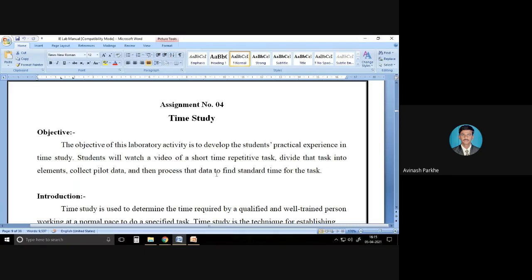How much time is required? 2 minutes. This is a rough value. Sometimes I can move from machine 1 to 2 within 1 minute, but the rough value we have decided is 2 minutes. That means in advance, before starting that movement, I have decided one rough value. Therefore, that method is called predetermined motion time study, which is also called PTS.